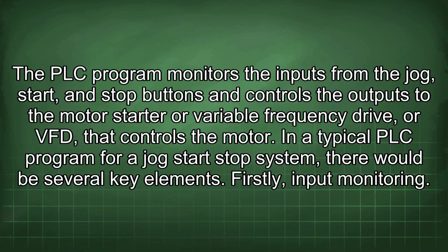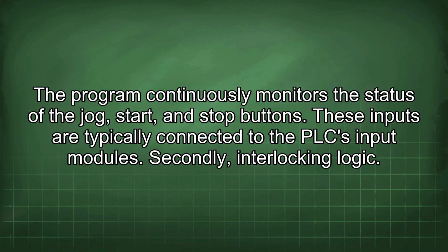In a typical PLC program for a jog start-stop system, there would be several key elements. Firstly, input monitoring. The program continuously monitors the status of the jog, start, and stop buttons. These inputs are typically connected to the PLC input modules.